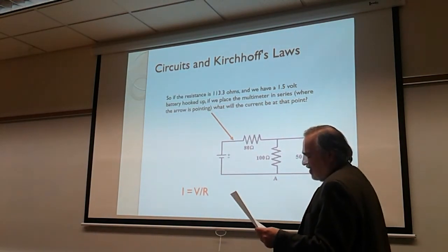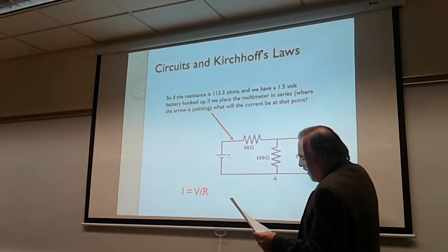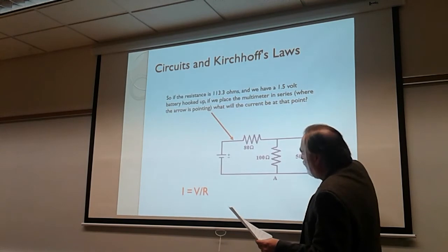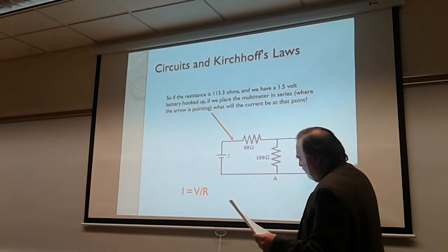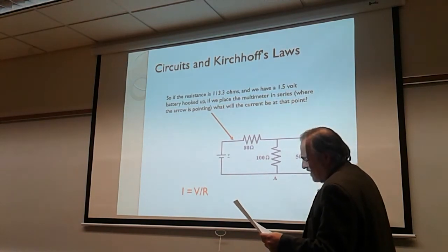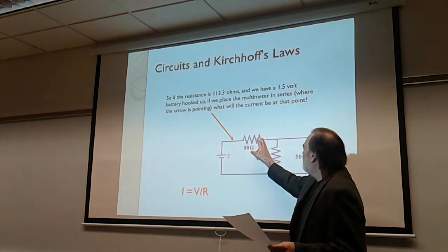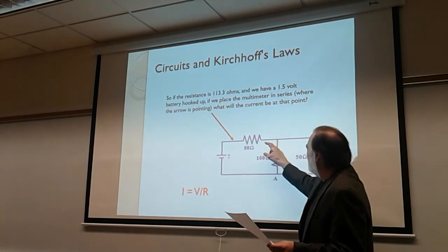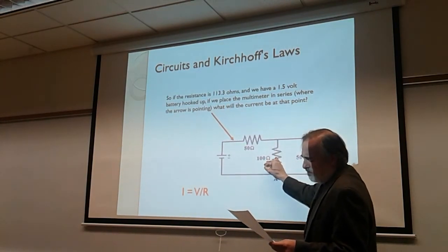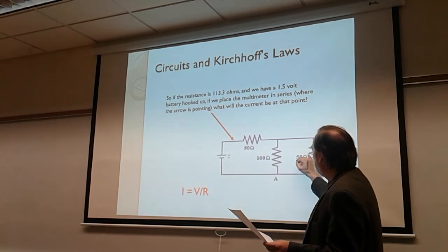Then into this junction, much the same way, I equals V over R, the V being 0.444 going in, divided by 50, giving us an 8.88 milliamps into this. Bottom line is the milliamps here, 13.2, gets split to 4.44 milliamps this way and 8.88 milliamps this way.